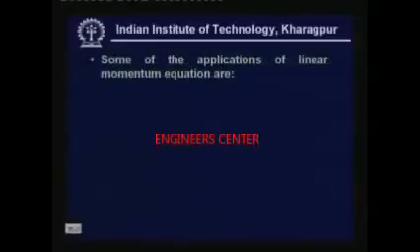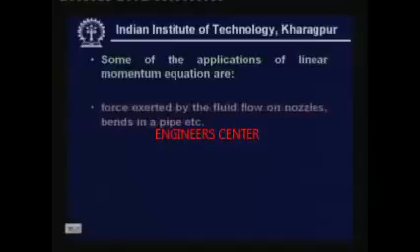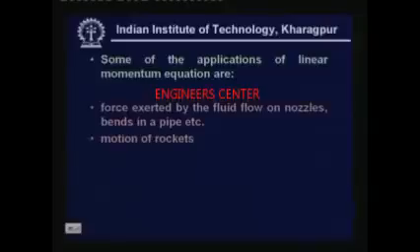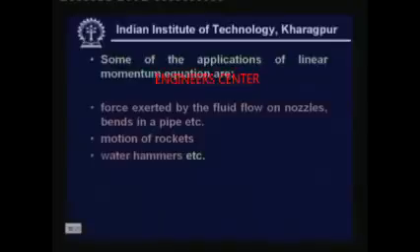Now some of the applications of the linear momentum equation are the force exerted by the fluid flow on nozzles, bends in a pipe, etc. That means we want to find out the force exerted due to fluid flow on nozzles and on the walls of the pipe and the bends. Then you have to apply the linear momentum equation. It is also applied to find the motion of rockets, and it's also applied in water hammers, etc.